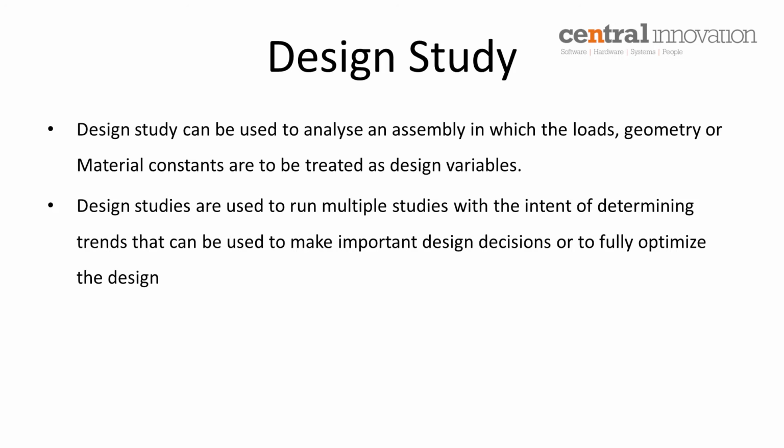By using design study, I can create multiple design scenarios, not loading scenarios. In the previous example, I explained and showed the Load Case Manager, where we can study our design for different loading conditions and loading combinations. You can create equations and create loading combinations. But design study helps you analyze different design scenarios, and all you have to do is choose your variable. So if this is going to be a variable, how is my design going to respond when the variable changes?